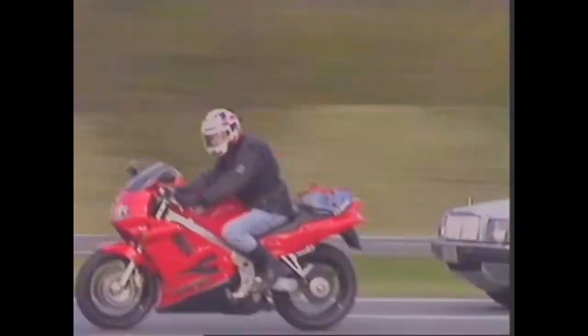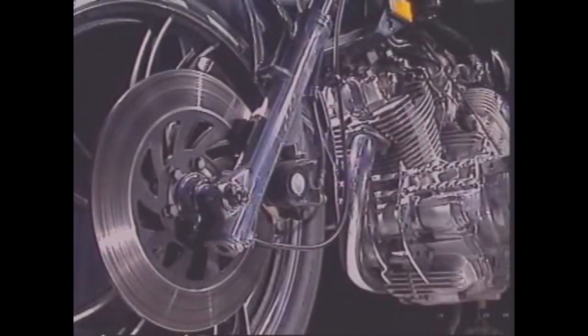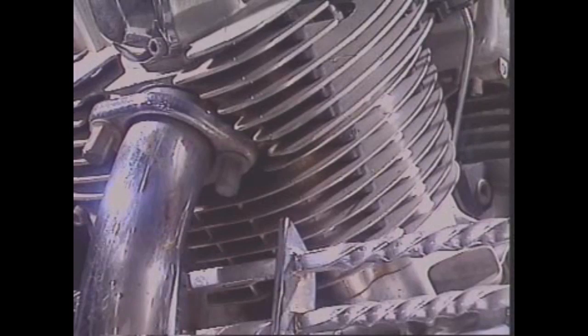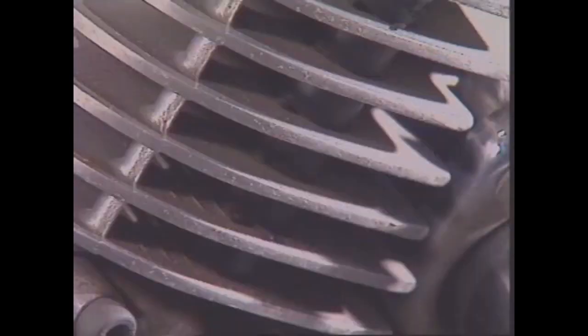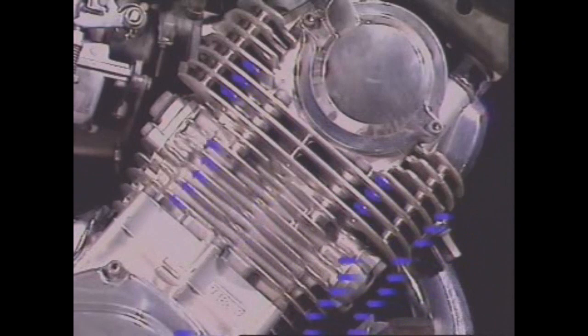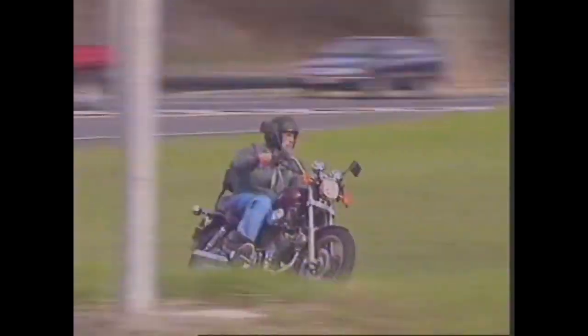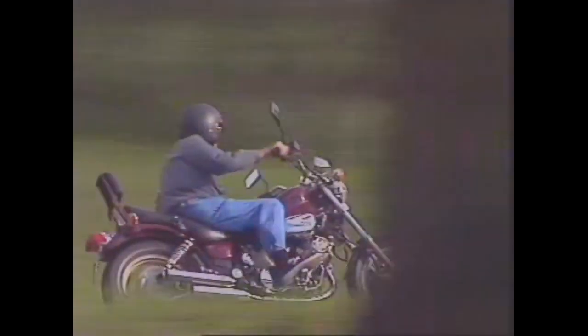Some engines use what are called cooling fins. Their design makes the exposed surface area as large as possible, which allows more heat energy to radiate away and be carried off in convection currents in the air. More air flows over the fins and more heat is carried away. For a vehicle moving at speed, airflow over the engine is high.